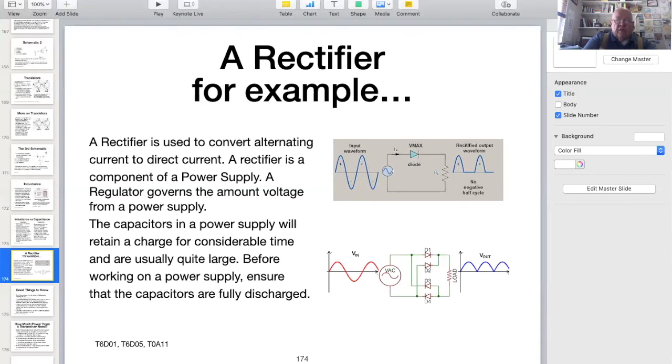The bottom diagram employs 4 diodes to make what is called a full wave rectifier. The result is twice as many pulses of direct current. If the input was 60 cycle current, the output will be 120 cycle current with no space between each of the pulses.